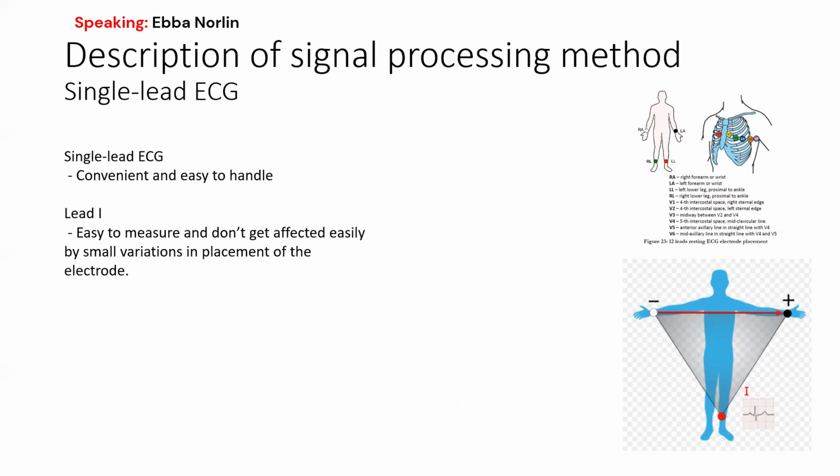So when sampling all of these ECG signals, we have two different methods. The most commonly used one, especially in healthcare, is the 12-lead ECG. It consists of putting 10 different electrodes on the person's chest, arms, and legs. These electrodes are like sticky plates that you push on the skin, and they transmit and record the signal as an electrocardiogram, representing the electrical activity of the heart's different parts, mostly atrium and ventricles, like Mobina told in the first slide, and how the wave is constructed. It's why it's called the 12-lead ECG.